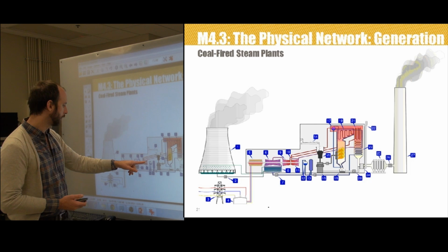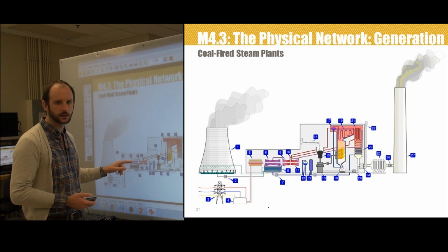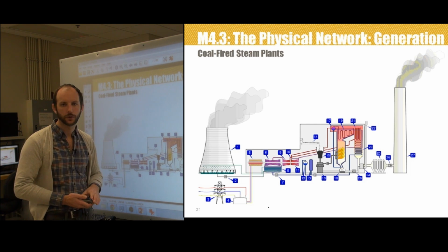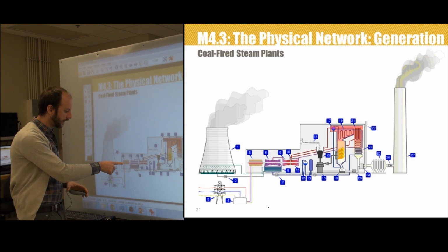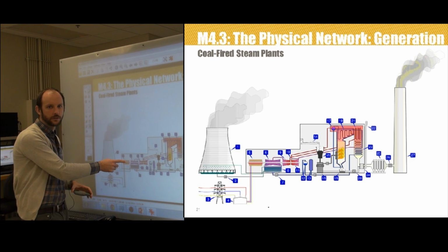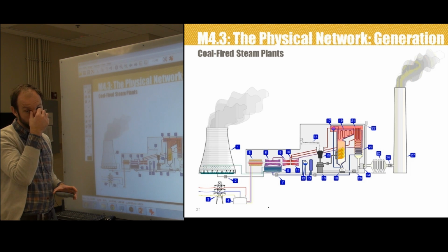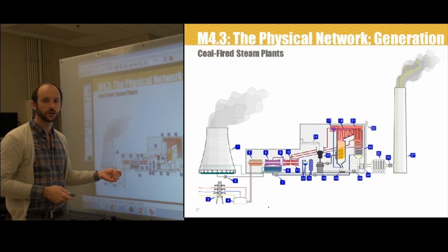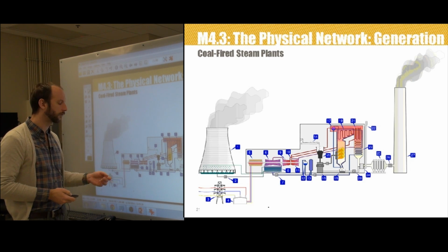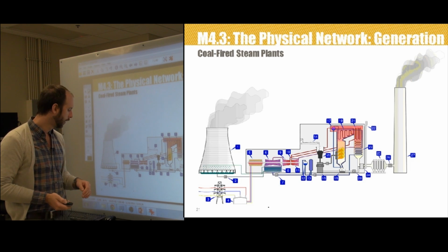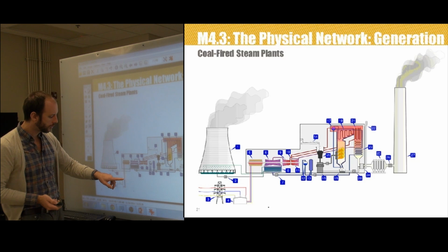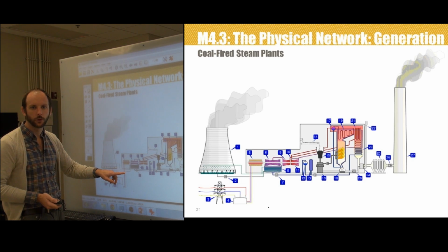The three turbines, 11, 9, and 6 here, the high pressure, intermediate, and low pressure turbines, are all coupled on the same shaft, and then they connect to number 5 here, the three-phase generator. That three-phase generator typically will generate an intermediate voltage between 20 to 25 kilovolts. It actually depends on the generator design, so that's just a rough figure. The output voltage is three-phase. We can see red, blue, yellow, the three phases.